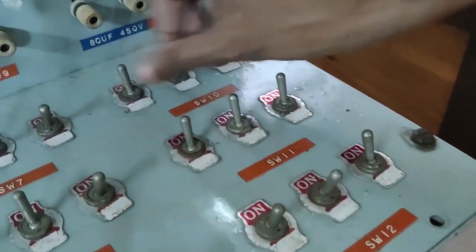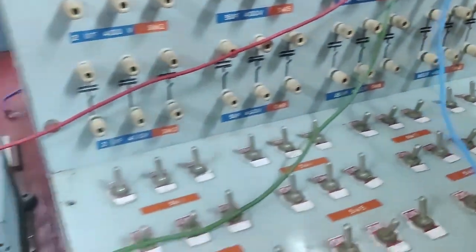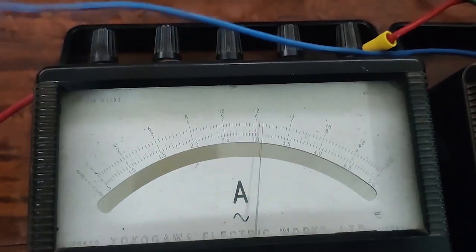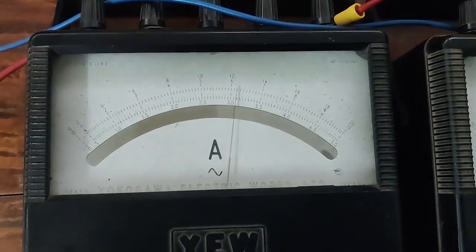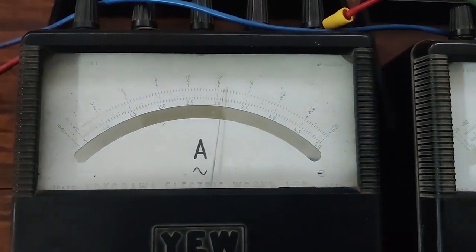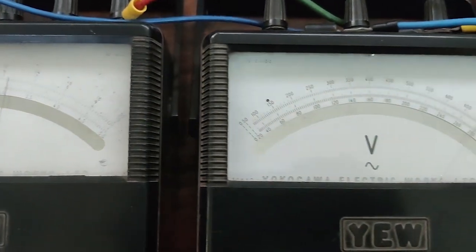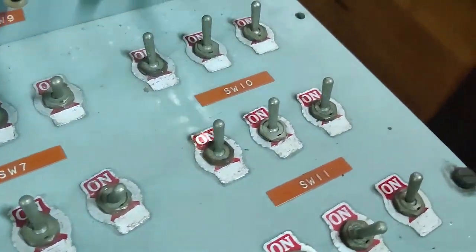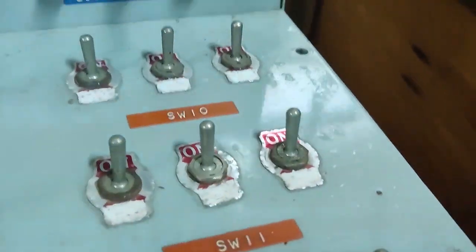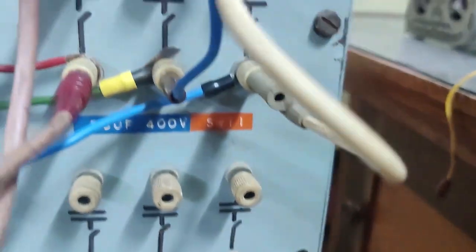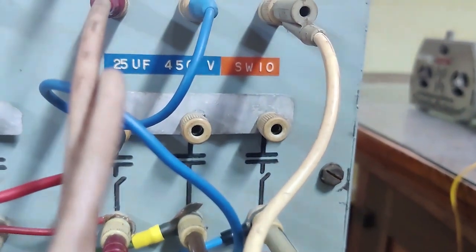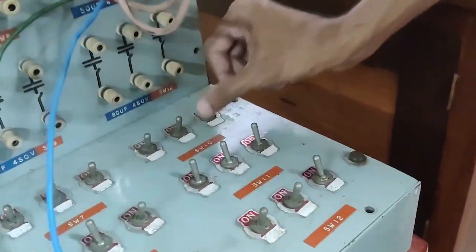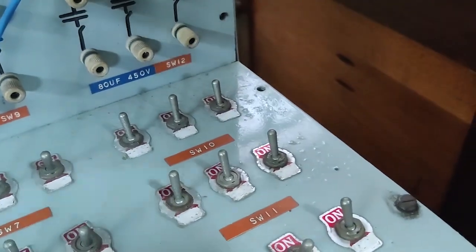Now connect the capacitor bank at the machine terminals and measure the voltage, frequency of the induction generator, and the magnetizing line current on no load at 2500 rpm. Make sure not to exceed 280 volts. Here we have connected the capacitance of 75 microfarad to the machine. Switch on the capacitance using these switches.